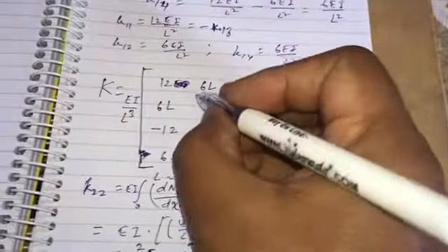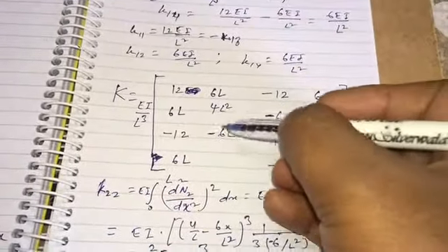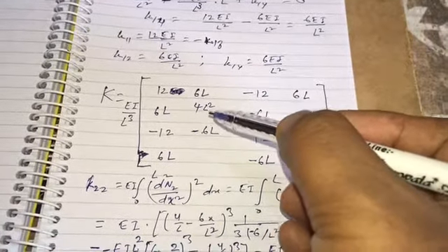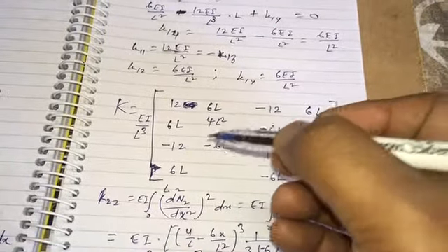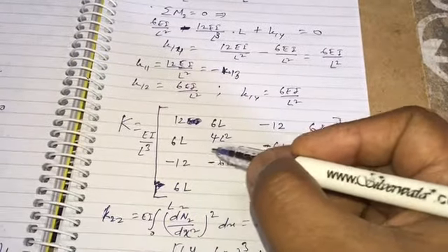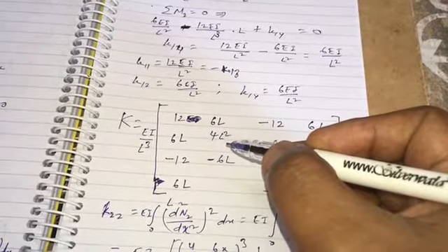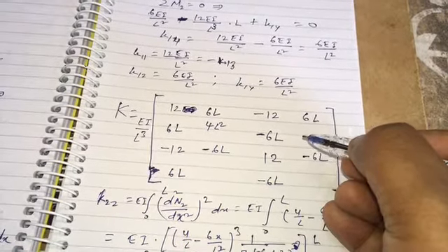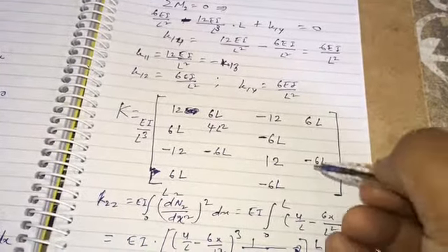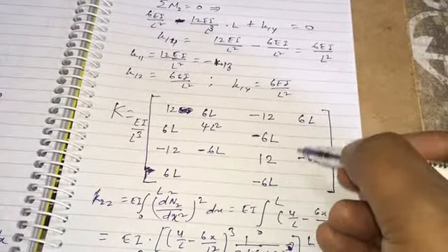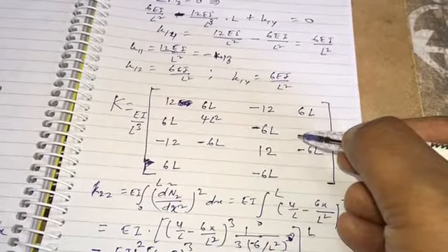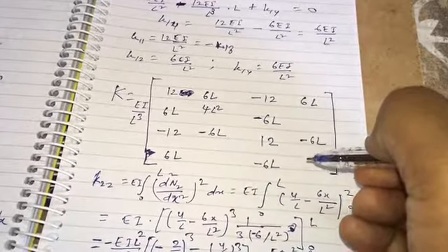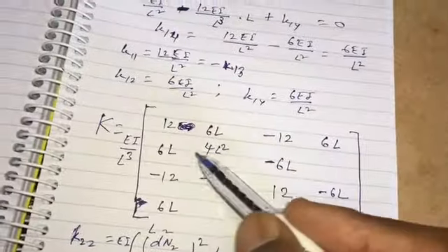So EI, so we write 4 here, then L square, because then you multiply with this and you get 4EI over L. So we get this one. Okay, now if K22 is 4EI over L, what will be the value of this one? For that we have to see the moment equation, accordingly do it. However, that we will do on the next page, but here if we have this value here, we can find out here based on the moment balance, and same value we will put it here, and here we will see what should be the value.